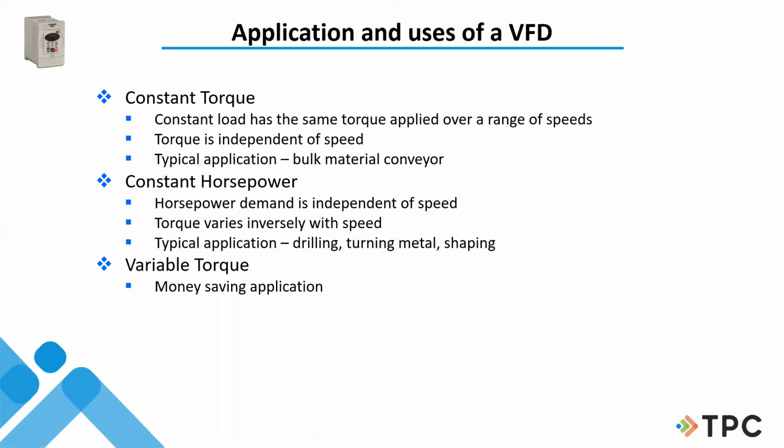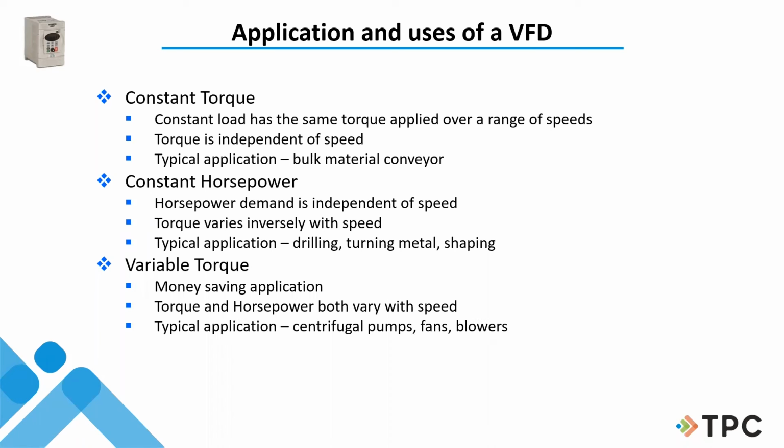Variable torque, as we talked about, is the money-saving application. A lot of pumps. And especially when it comes to pumps, I said earlier that a VFD is probably one of the great preventive maintenance tools you can buy for some cases, and this would be one of them. I don't have that jerk on the pump impeller anymore, or the bearings or the coupling.